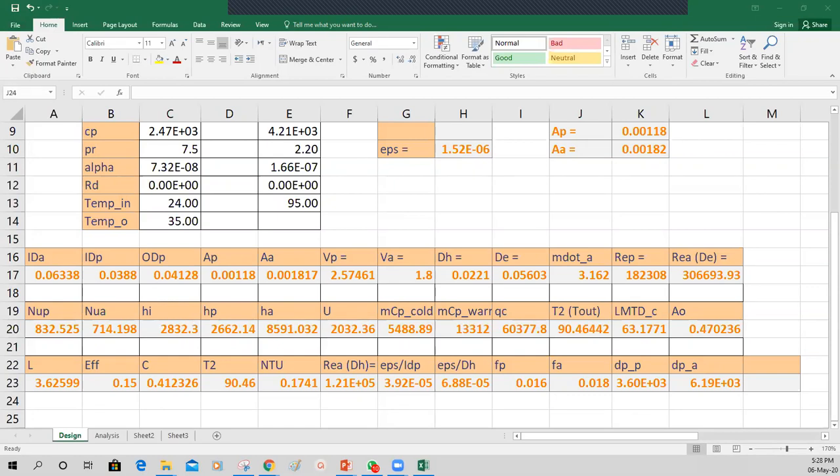Because we just calculated this is the capacity for the line heater, but if you don't want to use a line heater, then you can increase the time. For example, you want the same energy, but your time is doubled. When your time is doubled, then you can divide the capacity by 2. You can use half the capacity. The warm water will be stored in the tank, and you can use it.